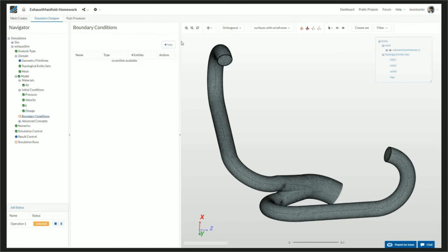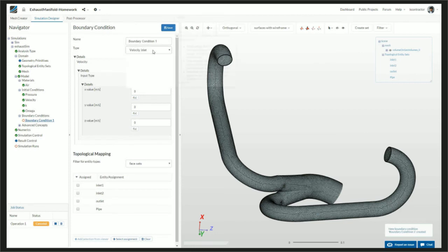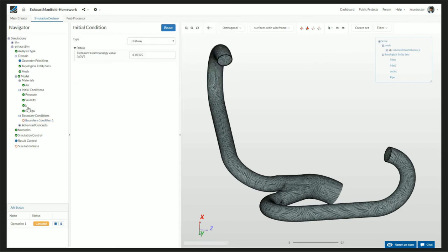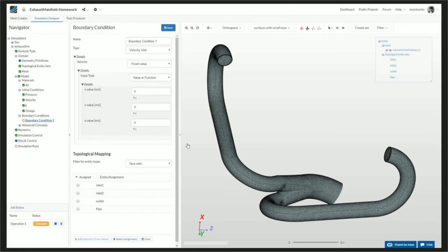They have been already set optimally for an incompressible flow. So you can leave them the way they are. Just in case you are making a very detailed simulation, you might want to calculate the initial values of K and omega, but they are usually calculated during the simulation. So it would not be a very big issue if you don't.